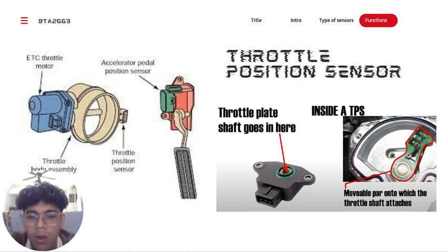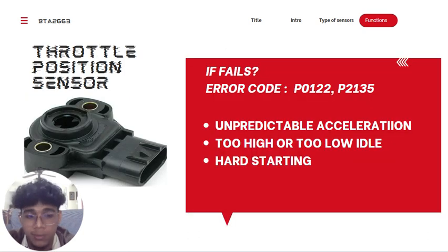Now, that is how an old throttle position sensor used to work, but today, a modern position sensor actually relies on non-contact position measurement and uses either Hall effect, induction, or magnetic resistance to do the same job as a variable resistor. Obviously, to measure the position of the throttle plate, the throttle position sensor must be located on the throttle body itself.